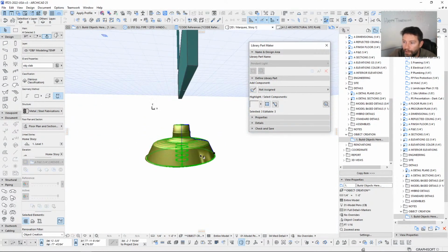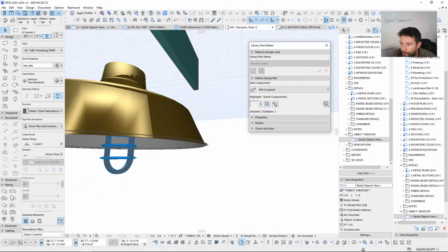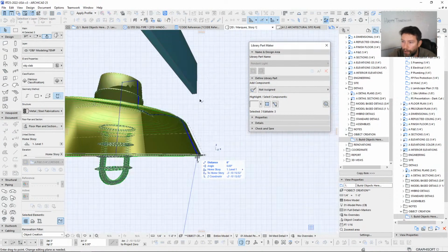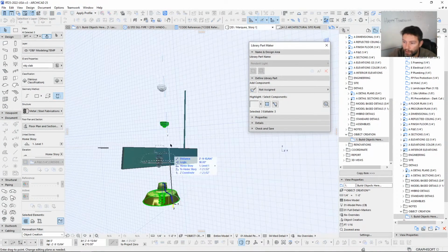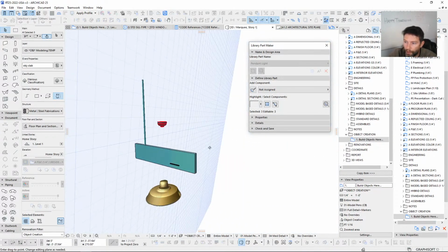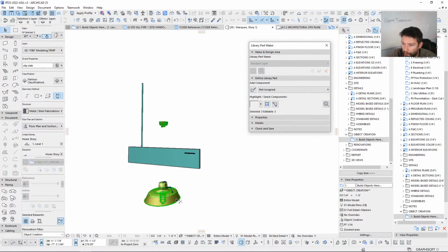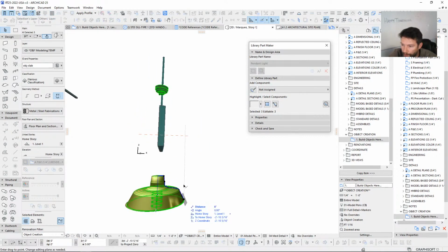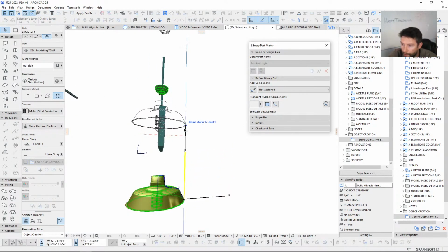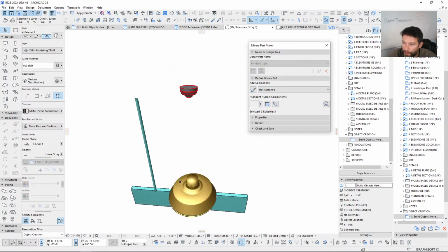And finally, when we're placing this, we do want to make sure that the bottom of our lamp is at 0. So this is the right time to grab our bottom point there, and we are simply going to bring this straight up. And I don't know why, we're going to turn off our reference plane there. That was a little strange. We are going to take this and snap this right to 0. So okay, now we are really starting to get close on this.